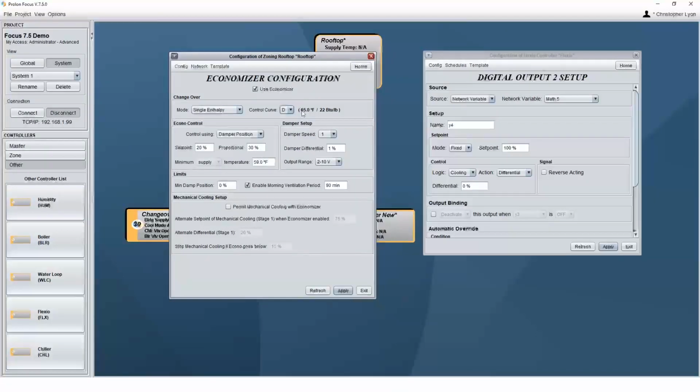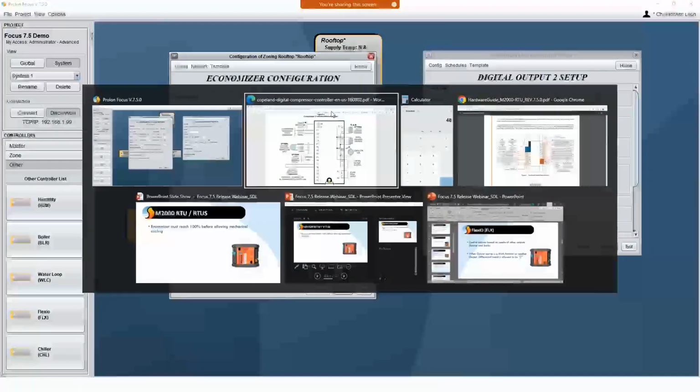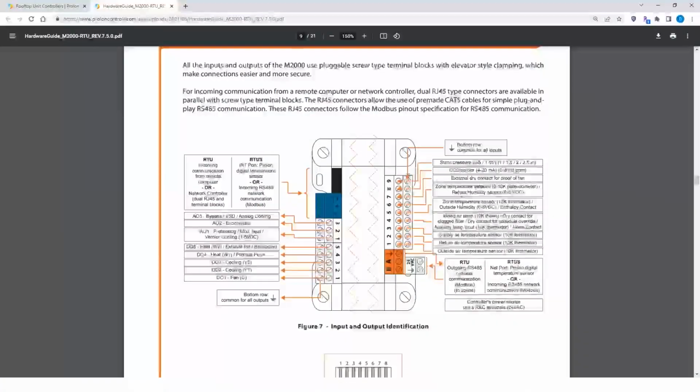You know, a lot of times we just kind of crank it to D and go with it, make sure that it's good air. Now, rather than accepting a single enthalpy signal that is representing your BTUs per pound of air, we actually will still take the dry bulb signal that we've had, and we are going to now have the option here on input 5 for an outside humidity on a 0 to 5 volt. Okay, we can also get an enthalpy contact. I'll touch on that in just a second.